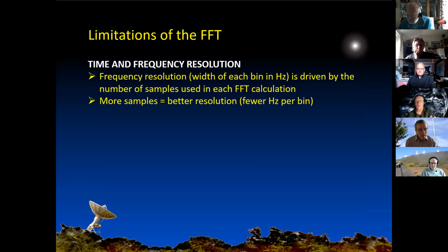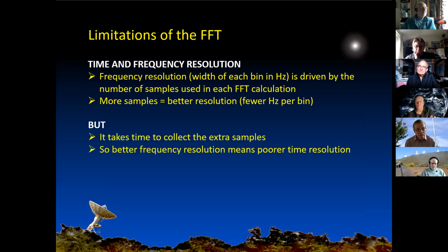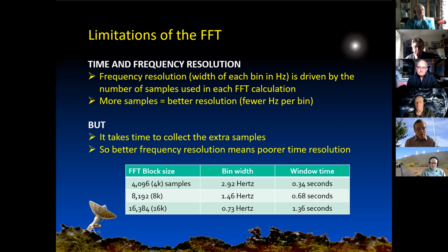Right, and then another limitation which I've alluded to is the relationship between time and frequency resolution. Frequency resolution is driven by the number of samples you use. So if you want to look at more detail of the spectrum, then you just feed in more samples to the FFT. But it takes time to collect those samples. These samples come into the system one after the other. So you've got to wait until you've got enough samples before you can set the FFT going. So better frequency resolution has a penalty, which is poorer time resolution.